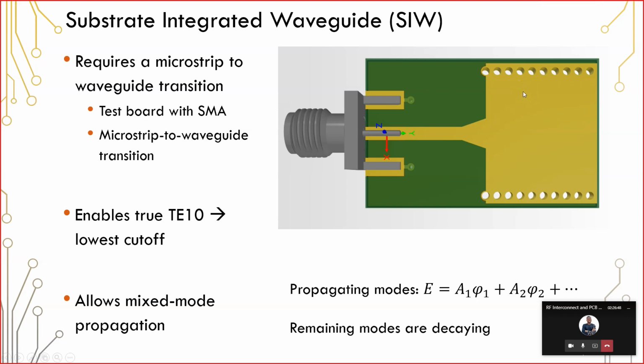a slot antenna. And that slot antenna can broadcast very strongly, even in a lossy dielectric like just a standard FR4 dielectric. And so I've actually built Wi-Fi transmitters based on this structure. And this particular structure broadcasts very strongly at Wi-Fi frequencies. If we were going to use it at much higher frequencies, what that would allow us to do is make the structure smaller. And then we would also want to use a low loss dielectric in that structure.